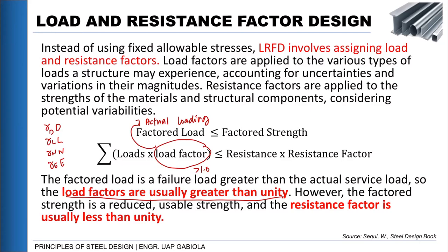Factored strength, it means na yung resistance or yung capacity ng mismong material natin, we multiply it naman by a resistance factor that is less than 1.0 to account for any uncertainties that may occur during the actual construction of our structure. So, by using these factors, sinasabi na yun nga, mas nasasaklaw ni LRFD yung actual condition na na-experience ng building once na na-construct na siya. And these factors are based from experience na we try to adapt so that we can create a more economical sections for our structure. Kaya yan yung tinatry i-work out nung LRFD na design philosophy.